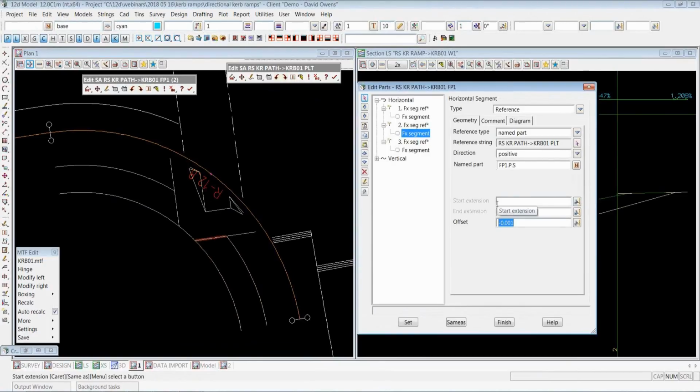And again, simply running parallel to the curb return as the first segment, second segment running parallel to that platform with a little bit of an offset. Now, I did go for that offset for a specific reason. When you've got strings exactly on top of strings and the points and segments are not actually identical, you can start to get crossing breakline problems coming through with your tin. It can start to look a little bit wonky.